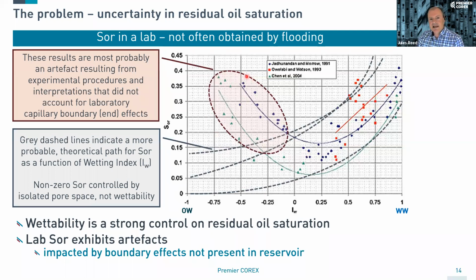And this data here is probably a function of core flooding processes where the artifacts, boundary conditions of the laboratory test have not been taken into account. So these are impacted by capillary pressure interfering with the relative permeability core flood, and really should be down here, but it requires much larger forces and much longer throughput times to achieve the residuals in here.